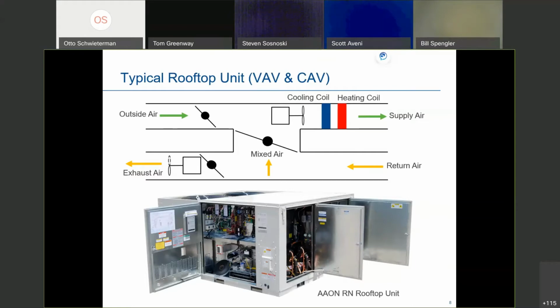So if you have a lot of air pressure in the building, it's overpressurized, you may have problems such as the doors may not shut. Open the door and try to shut it, slowly opens back up. Stuff like that would be a good instance of overpressurization. So this exhaust fan really helps with that aspect.